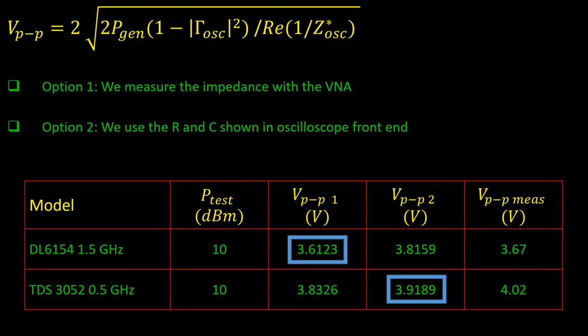It depends on the value of the impedance we measure. We see that the poor estimation of the parallel resistance from the measurements done with the network analyzer does not have any strong influence on the final values of the voltages. Consistent values are actually obtained since the slight underestimation of the reflection coefficient magnitude is partially compensated by the underestimation of the oscilloscope conductance.